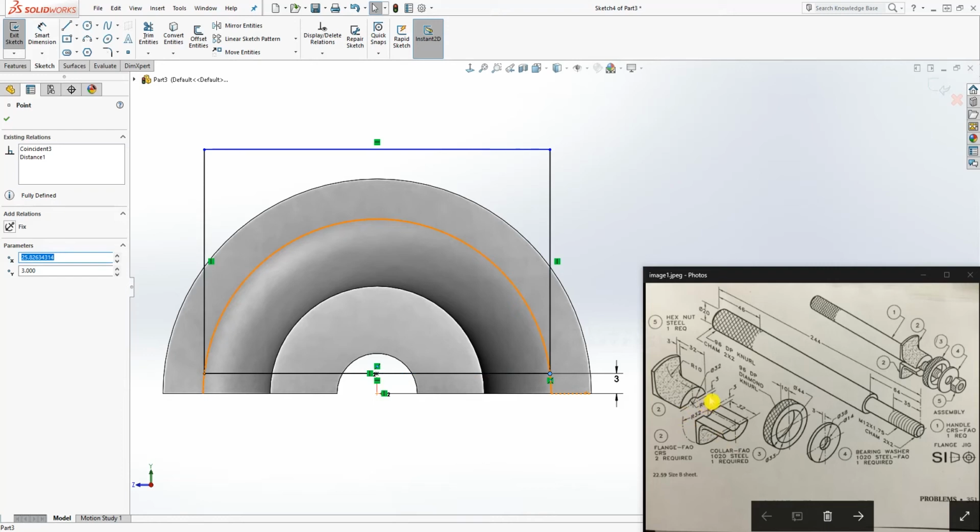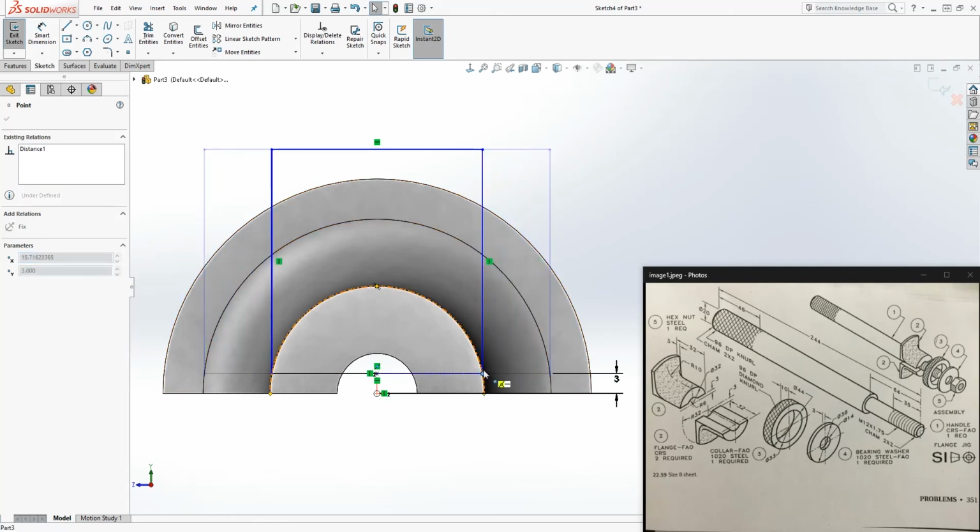You just gotta think about how the drawing looks. So this 3 point is coincident with that part at the 3 point. It is coincident with this edge, because if you look at it, this edge is going back that way. So if you look, it's more apparent over here.